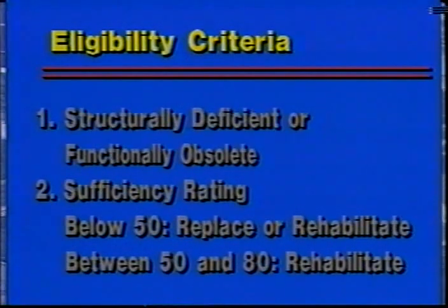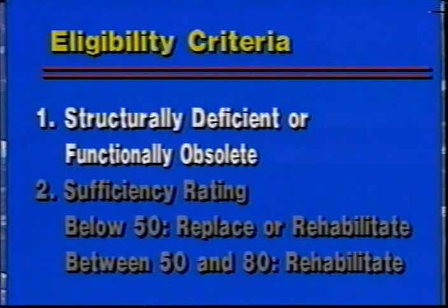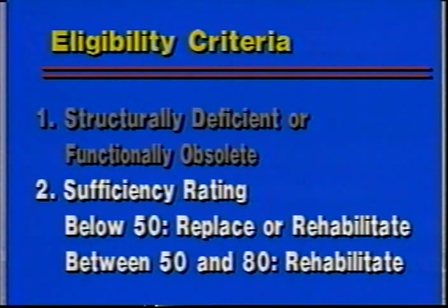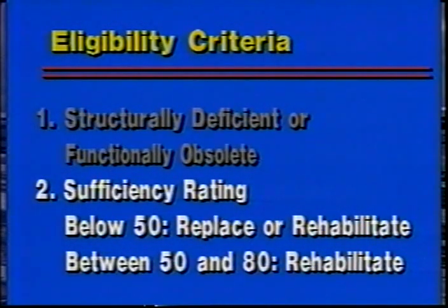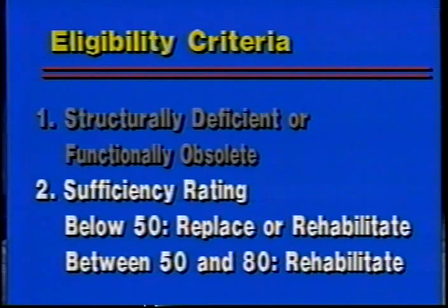Bridges that are either structurally deficient or functionally obsolete are eligible for consideration for matching funds under the Federal Bridge Program. Those with sufficiency ratings below 50 may qualify for replacement or rehabilitation. Those with sufficiency ratings between 50 and 80 are eligible for rehabilitation only.